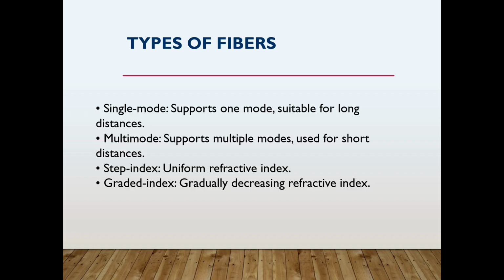These fibers are ideal for high speed data transmission, and they are used in applications like high bandwidth internet connections and optical communication systems. They offer reduced dispersion because the gradual change in refractive index in them minimizes modal dispersion. This allows for better performance over medium to long distances and higher performance compared to step index fibers. Graded index fibers support higher data rates and are more efficient at transmitting light over longer distances.